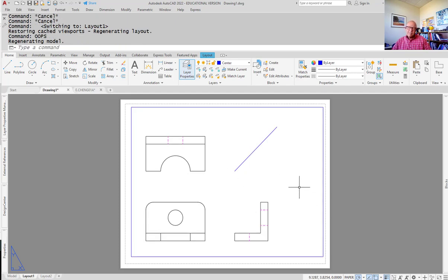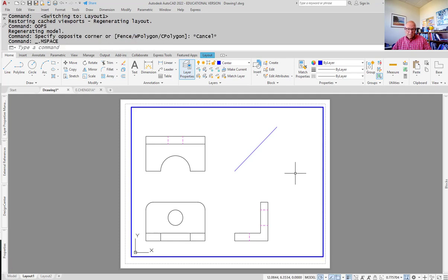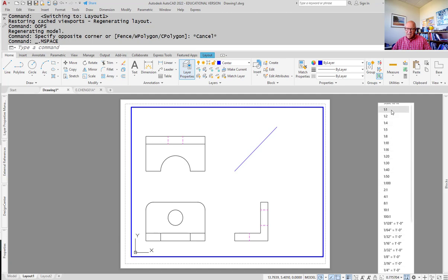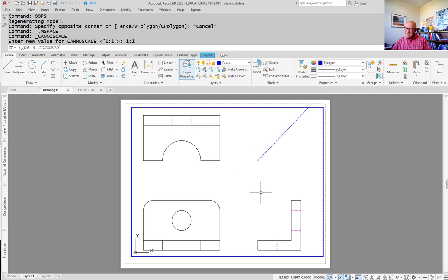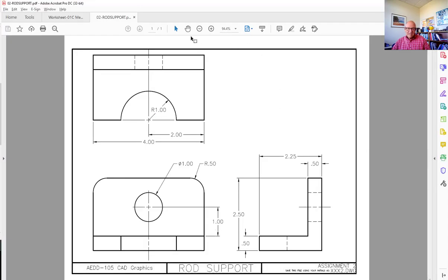The key thing we have to do here in this layout is find out what scale can be used for this. The scale that can be used for this, we hope, is 1:1. So I double click in here, I go down to the bottom, and right over here there's a number, and if you hover over it, it says scale of selected viewport. Well, that's not 1:1, so if I pick 1:1, it gets bigger, and I think, no wonder the handout has such a small title block, because at a 1:1 scale, there's not enough room for a real title block.